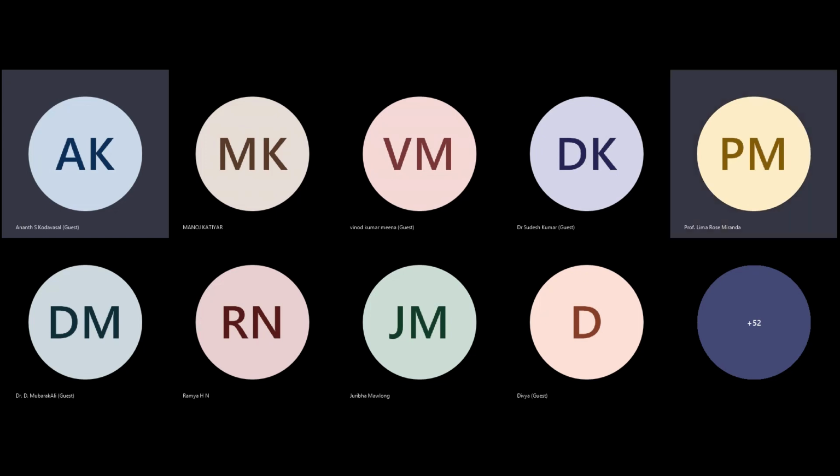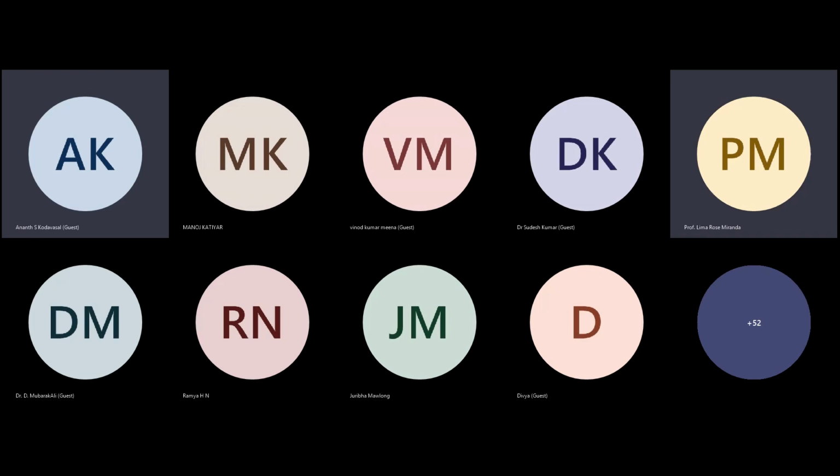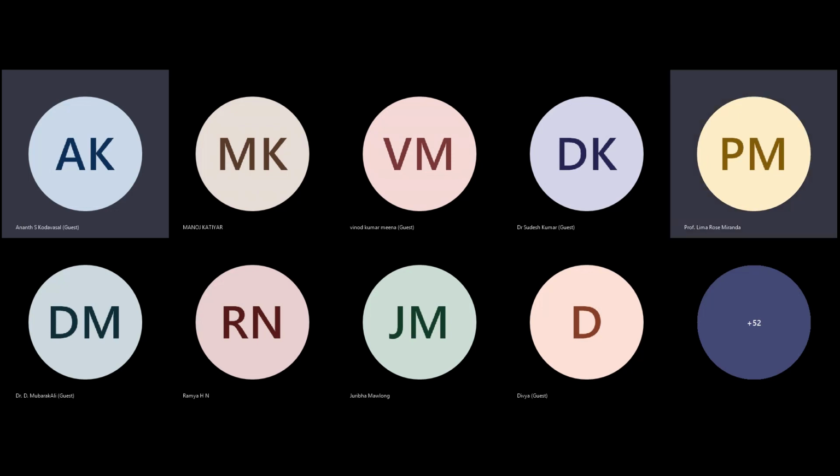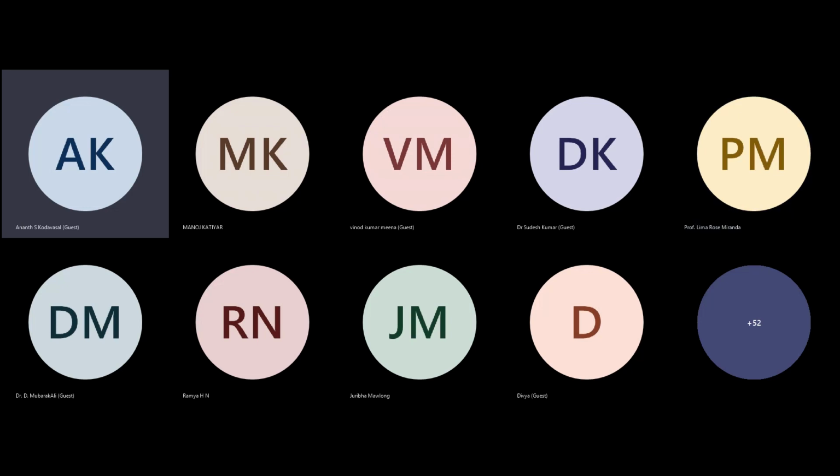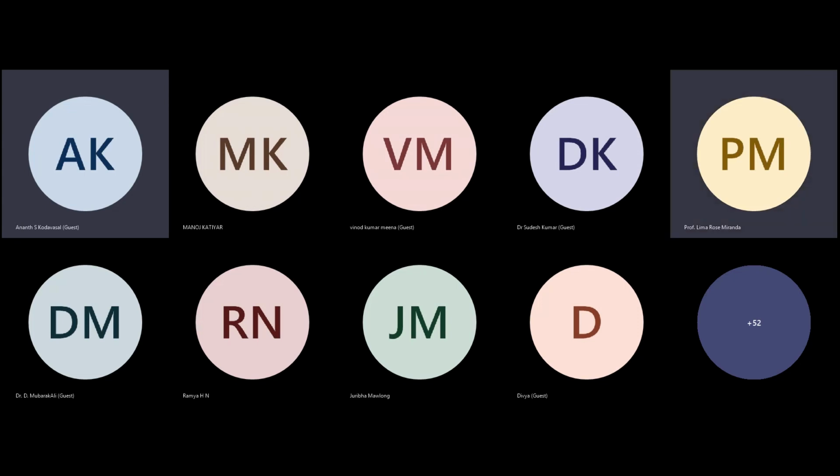I have a small additional presentation on that, because MLR recycle is very, very energy intensive. So you have to optimize that energy consumption, and you take into account all the advantages that the aerobic treatment plant provides. There is a contiguous nitrogen removal as you remove the BOD itself, and therefore only the remaining nitrogen has to be controlled in the anoxic denitrification stage.